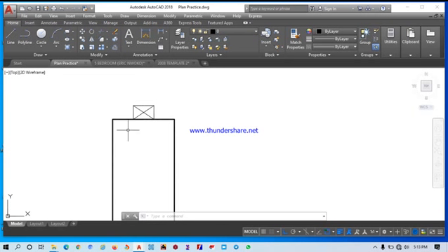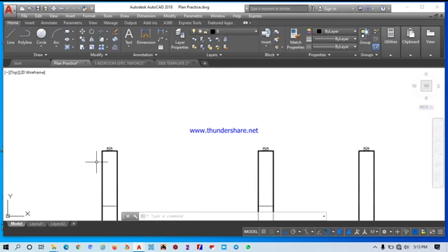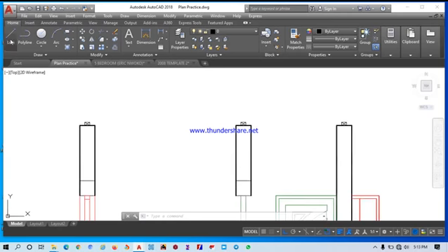If you are having a roof beam, you might break your block at this area and just tie them. So it's on this wall plate that you tie that steel member to the wall plate and lock it to your wall so that the roof will not be able to blow away your building. So the next is